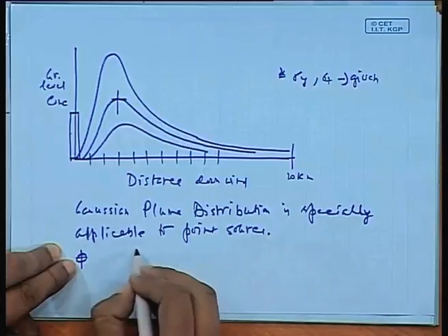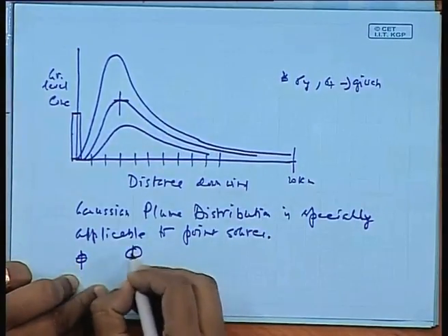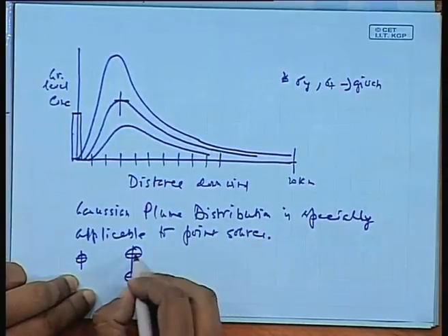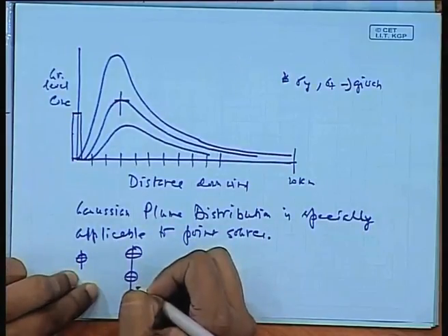But this Gaussian plume model can also be used for finding out line sources, where the points are on a line. These are essentially point estimations, but considering that the points are in a line, we can find out the concentration from line sources also. In that case, we manipulate the XYZ coordinates to identify a particular point, and calculate the likely concentration there from different sources, and the contribution of the different sources.